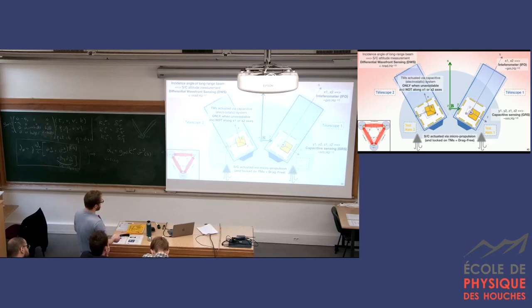So this is drag-free, but sometimes you see, because of especially gravitational interaction between the spacecraft and the test mass, this is one of the major sources of noise. Actually, it's crazy to see you have a 1-ton spacecraft that can generate an appreciable gravity field for the test mass. So this can cause a drift between the 2 test masses, and in that case, you cannot correct that with the motion of the spacecraft, right? You need to do something and apply force on the test masses.